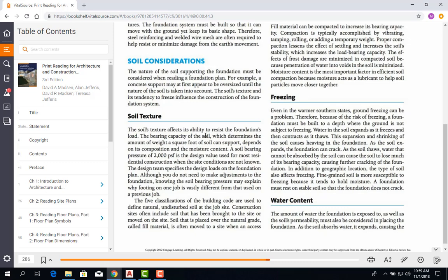you need to be aware where it is that you're building or erecting your building. The soil, you need to know what's underneath the ground. You need to know if the soil is stable enough to support your building. It makes a big difference if you design a foundation system for here where we live, South Texas. It is way different if you're designing for someone that is going to build up in Montana or in New Mexico or even here at the beach. So the soil makes a big impact on your foundation design. So you need to know what's underneath.